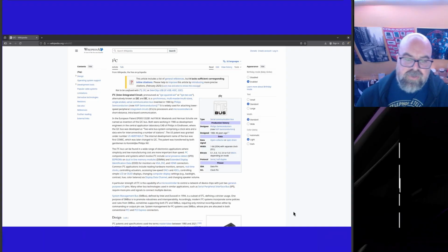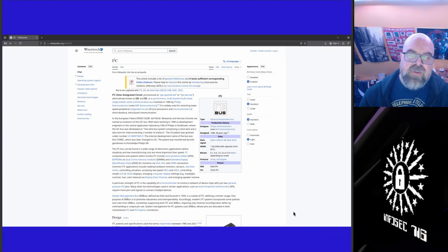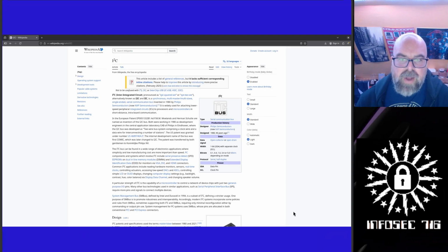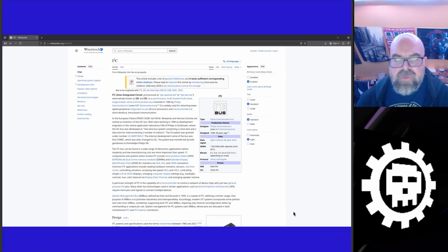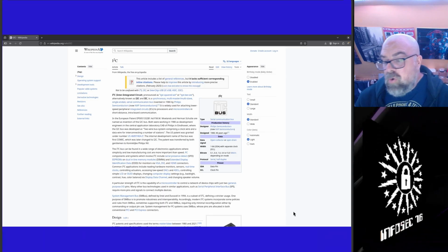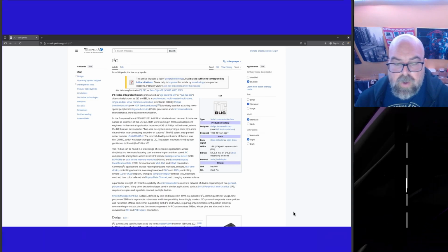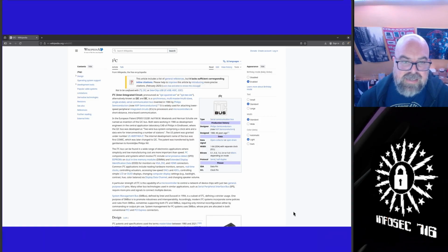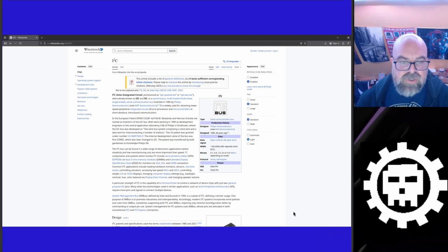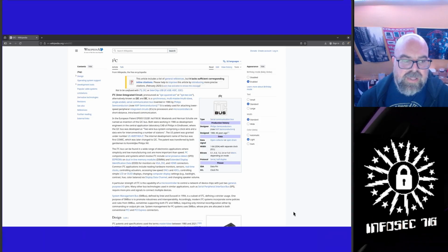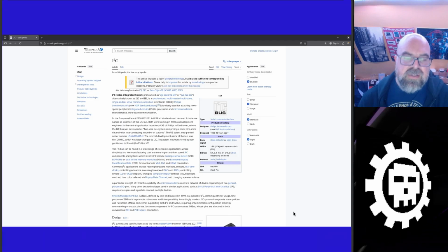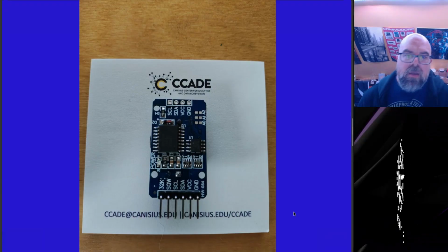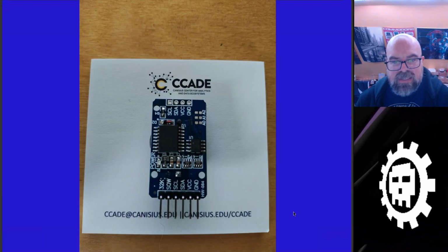And then there are a bunch of subsidiary devices, targets, each of which has an individual address, and you're able to interact with them over the I2C connection. This is really cool because I2C requires 4 wires, right? Power, ground, clock, and data, and that's it. Every device uses those same 4 wires, so it's really easy to add devices to the bus so long as they have unique addresses. The particular device that we're adding today is one of these.